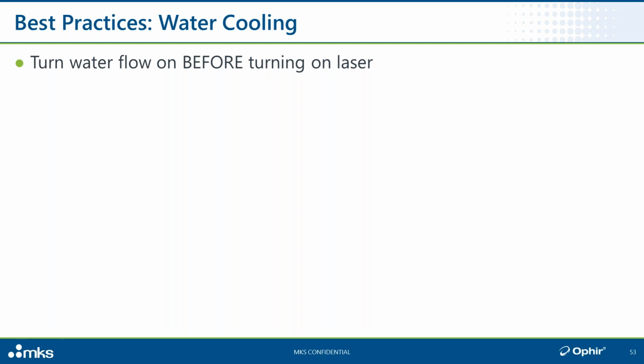With high power beams, it doesn't take very many seconds to heat your sensor up to the point of zapping it, if it's going to take a few seconds after turning the laser on before the cooling water starts flowing through the water channels. Turn the water flow on before turning on the laser.